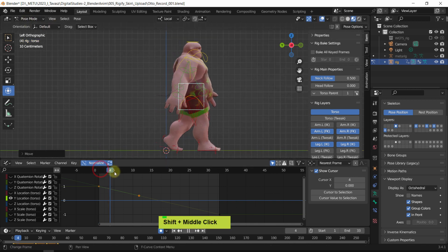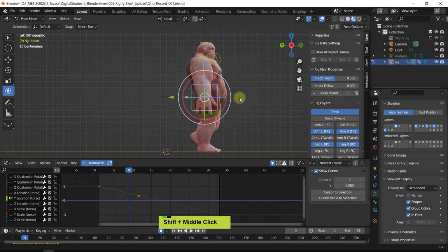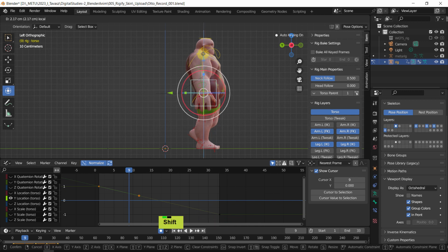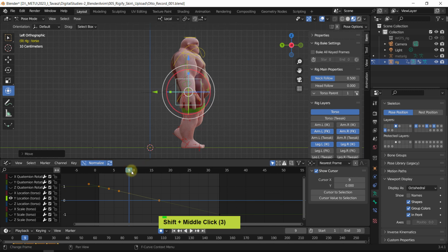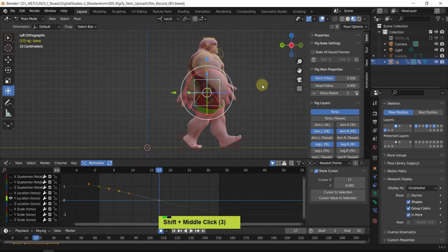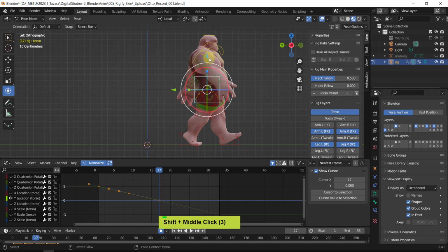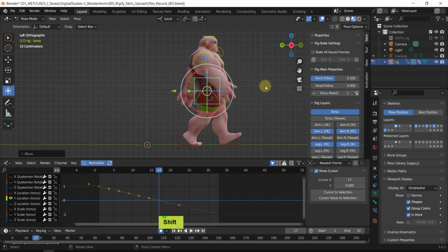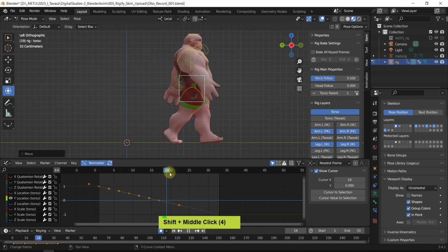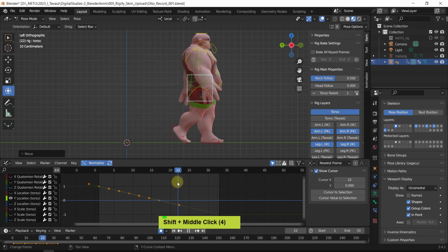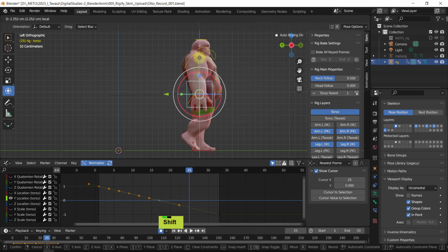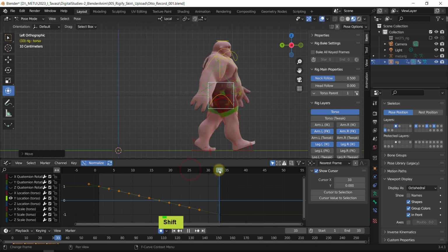It's really not much. And in the passing pose, which was at 9, I will give it back. So pulling back, start using the Shift key and pulling back about 2 centimeters. That's it. So here we are at 17. Again, this is a contact pose. I'm moving it holding down the Shift key to adjust about 2, which was great. So now there is a very, very soft movement. At 25, this was again pulling this up about 2 centimeters, nothing more. And at 33, it's going back down.